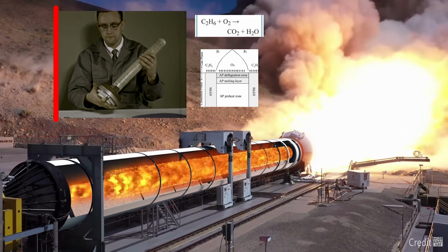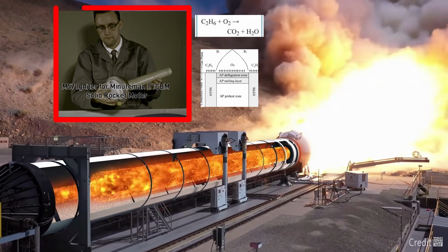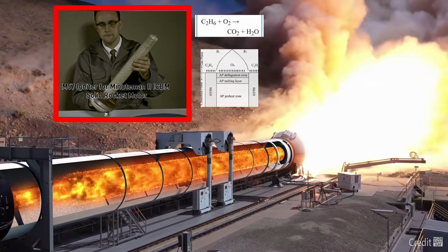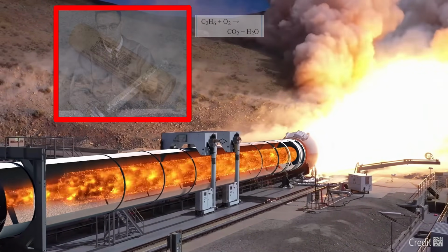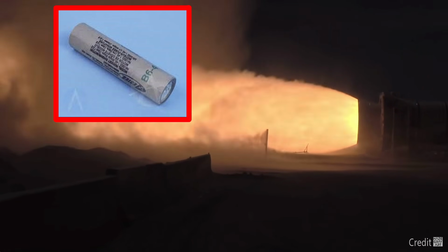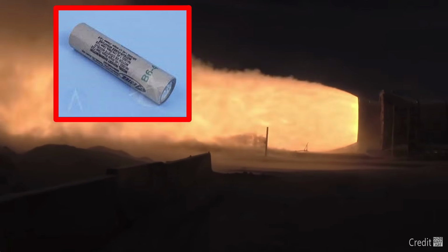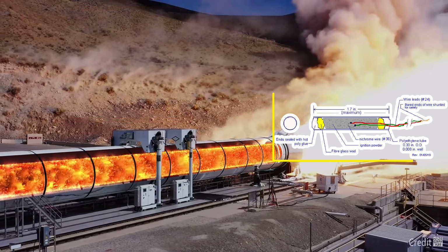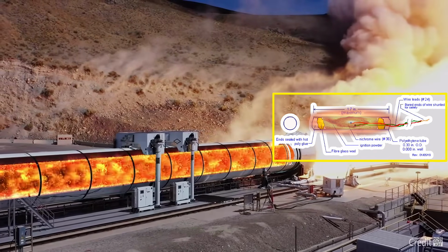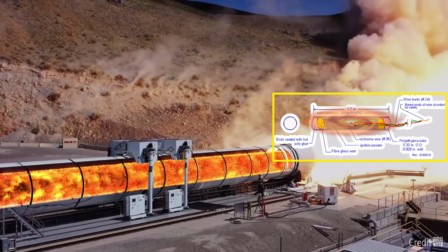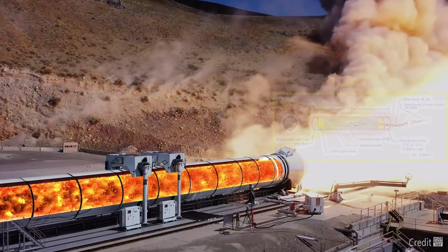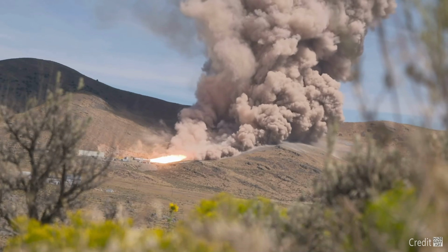They need an igniter. Here is the M57 rocket motor igniter assembly. This is like a large model rocket motor, which, if you are building and testing a new rocket engine, is one of the simplest ways to reach ignition. Simply install a small rocket motor with its electric heating element in place, and when electricity goes through the heating element, it will glow white hot. This will reach ignition temperature for the little motor, which will burn for several seconds. The heat generated by the little motor can ignite the large solid rocket motor.